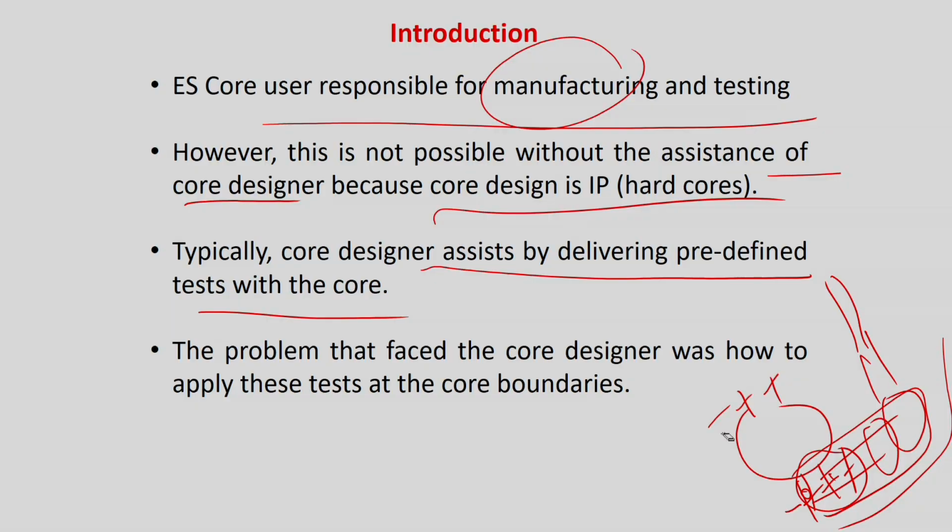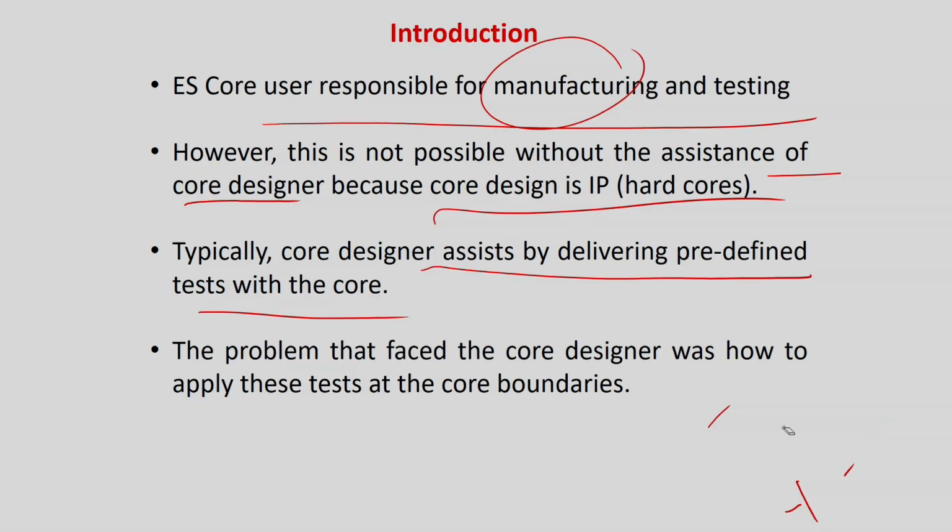Again repeating, because this is what is to be emphasized in embedded system core based testing: test pattern generation is not the problem. People are giving me the test patterns, and I am putting them in a single die. My point is only how to access these lines. As I told you, it's not a PCB based design, the chip is manufactured after putting all these cores. So there should be some kind of protocol and standard for how to access these internal pins, how to apply the test patterns and how to observe these responses, right? So the problem faced by core-based design was how to apply these tests at the core boundaries.